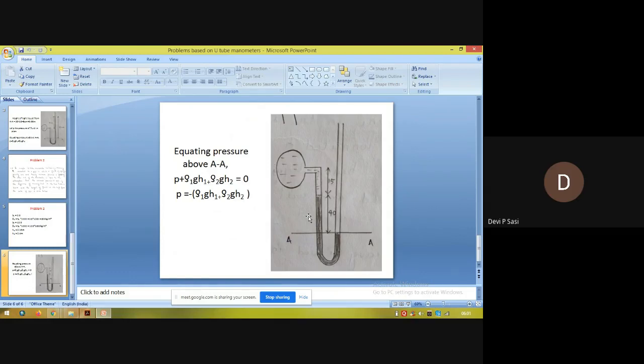Okay, that is clear about the heavy liquid. Now coming to the light liquid, it is given that it possesses a specific gravity 0.8. And the height of the fluid in the left from the center of the pipe is 15 centimeter below. So again, the light liquid possesses a difference of 15 centimeter. The difference in mercury level between the left limb and the right limb is given as 40 centimeter. It consists of two limbs, left limb and right limb, and the difference of mercury between the two limbs is 40 centimeter. That is already given.